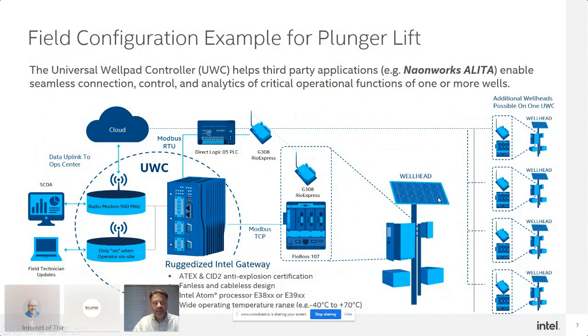So you typically would expect a low power operation at the edge. One reason is that a lot of these things will be run off of solar panels and lead acid batteries even today. The ruggedization of the hardware is critical, and so class 1, division 2 explosion proof certifications are typically required. Sealed devices and a wide temperature range of operation are critical.